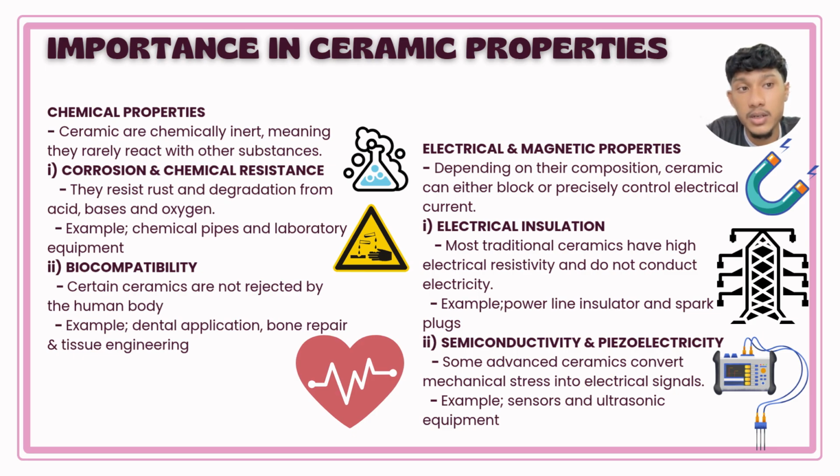Finally, we have the electrical and magnetic properties. Most ceramics are electrical insulators, meaning they do not conduct electricity. This makes them very useful in power lines, insulators, and electronic components like spark plugs. Some advanced ceramics also show semiconductivity and piezoelectricity. This means they can convert mechanical energy into electrical signals and vice versa. These properties are important in sensors, sonar systems, and ultrasonic devices.